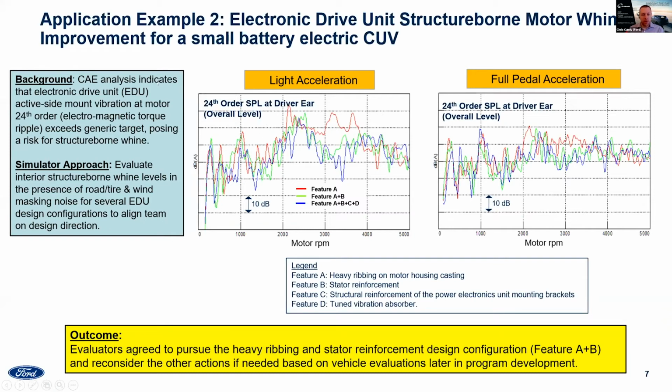The CAE model was predicting mount vibration, and there were several different structural design features being considered for that electronic drive unit. And so what we wanted to do is use the simulator and listen to the structure-borne whine in the context of the full vehicle. So when you add in the road, wind, and tire noise and wind masking noise,